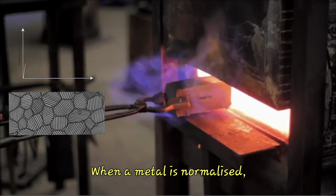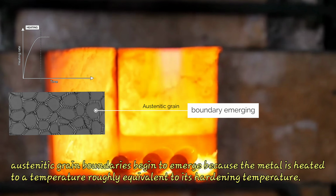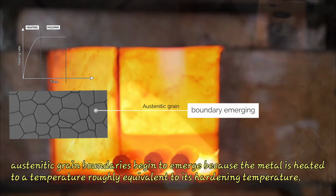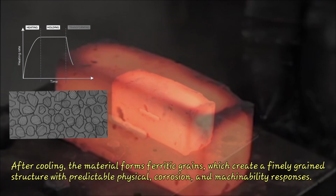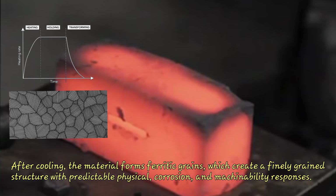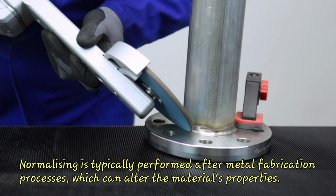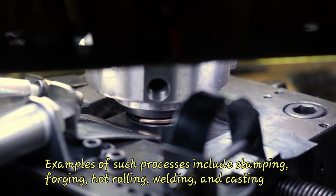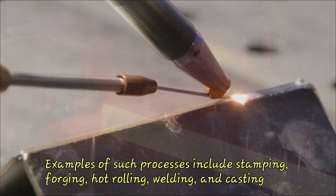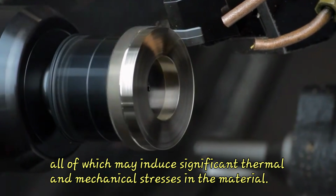When a metal is normalized, austenitic grain boundaries begin to emerge because the metal is heated to a temperature roughly equivalent to its hardening temperature. After cooling, the material forms ferritic grains, which create a finely grained structure with predictable physical, corrosion, and machinability responses. Normalizing is typically performed after metal fabrication processes, which can alter the material's properties. Examples of such processes include stamping, forging, hot rolling, welding, and casting, all of which may induce significant thermal and mechanical stresses in the material.